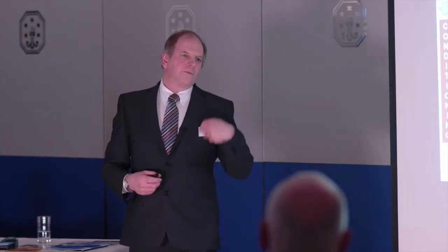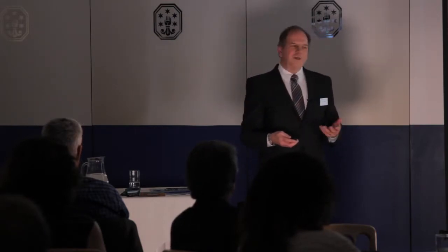Now, even stainless steel is a mild catalyst, so you are going to get some breakdown by surface reaction. So you do need a replenishment, which is why you need to not get into micro-condensation that's visible, but get into this micron deposition, whatever you like to call it. I tend to just call it VHP these days because apparently you can't register a trademark that's such a common term. You can register Hoover, but you can't register vacuum. So everybody knows what you're talking about when you talk about VHP, but that's how we are.